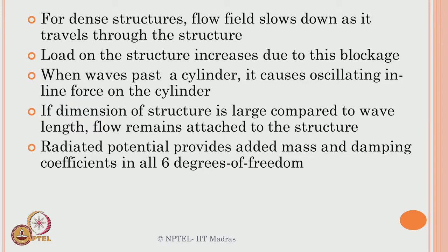For dense structures which are closely spaced, the flow field slows down, we already saw that yesterday, as it travels through the structure. Load on the structure therefore increases, what we call the blockage effect. We already said what the component of blockage effect is. When a wave passes the cylinder, it causes oscillation, inline force on the cylinder. If the dimension of the member is too large in comparison to the wavelength, flow remains attached to the cylinder.